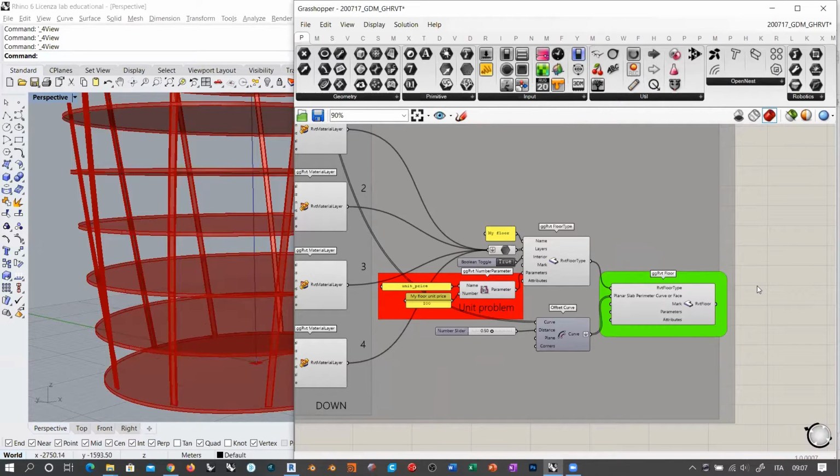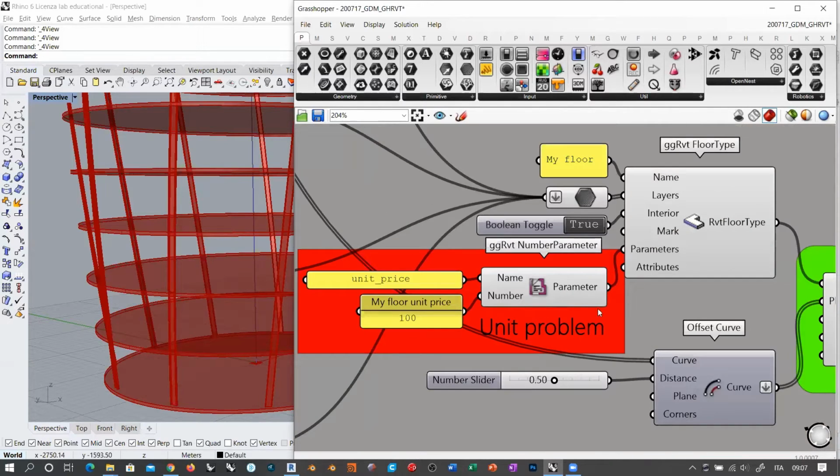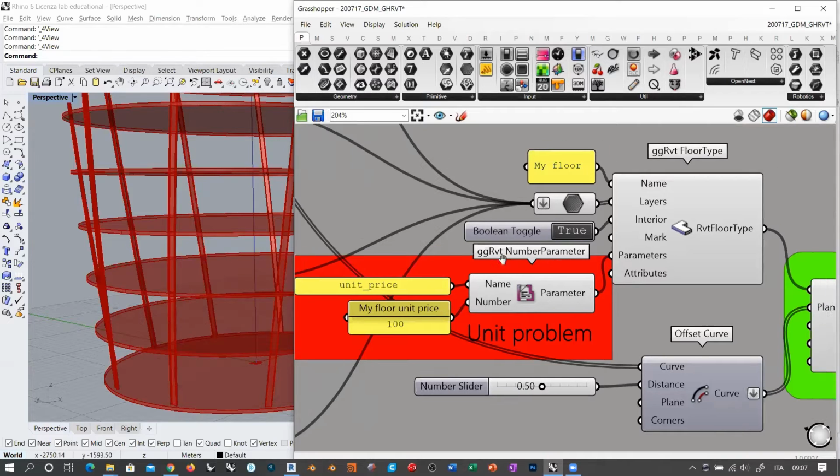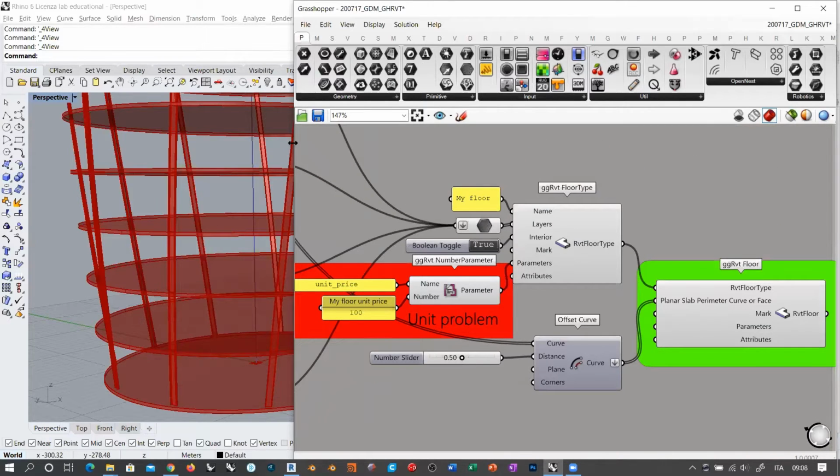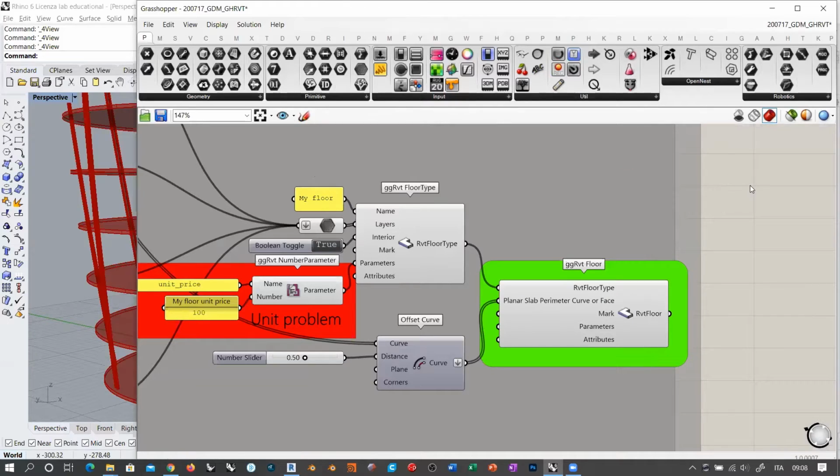But as I told John also, some users prefer to maintain everything inside Revit. So instead of producing a hybrid documentation between Grasshopper and Revit, it would be better to have this kind of information also available in Revit itself. So you can create schedules and quantities directly inside the other software, and therefore he is going to implement another parameter, which is going to be something like cost price, with the proper units, exactly like the measuring units: length, area, and volume.